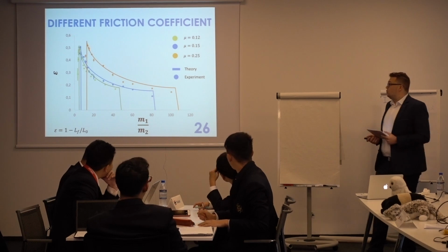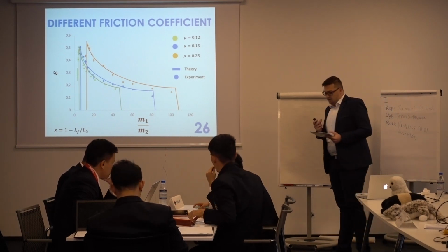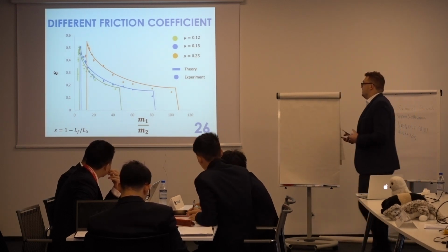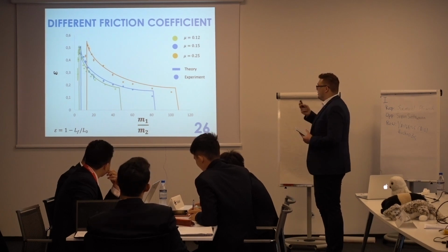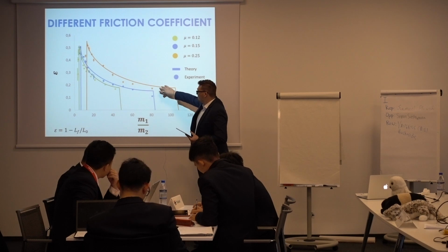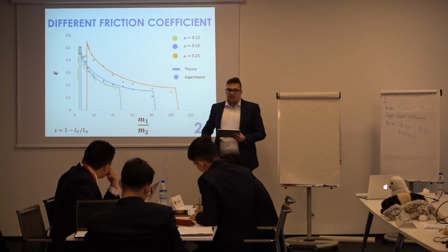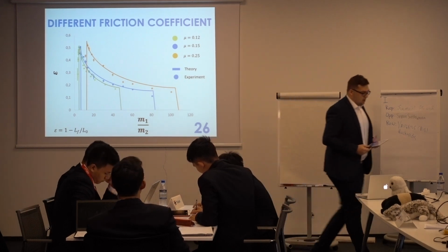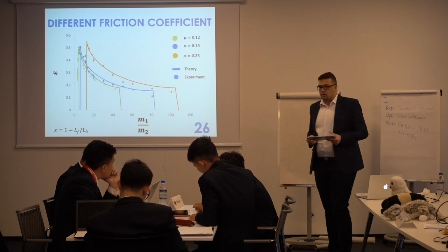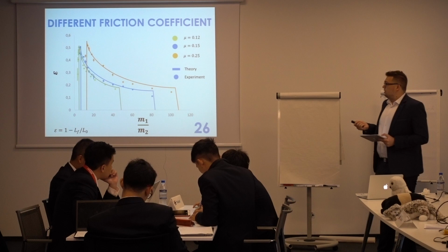Next, we can compare our dependencies measured with different friction coefficients, and we see that it compares fairly well. However, there are some discrepancies: the theory overpredicts the experiments a bit, due to, we believe, air drag that was not calculated in the theory.